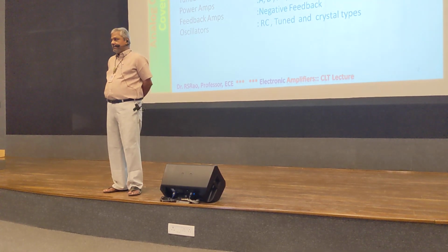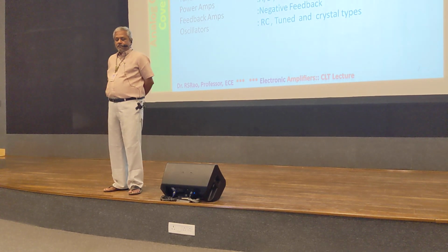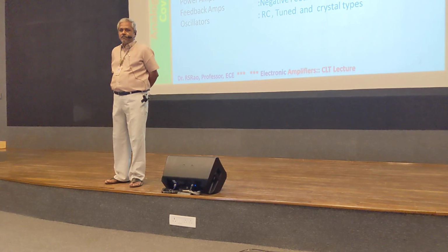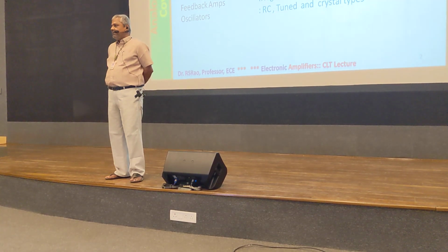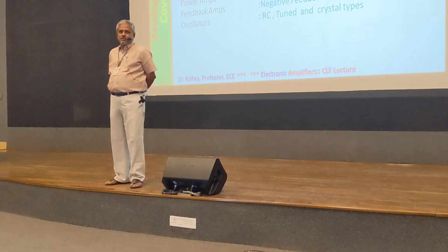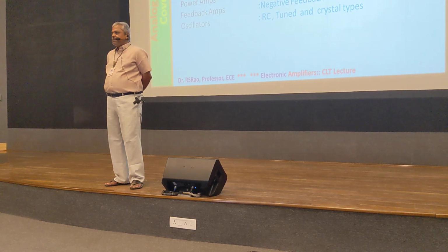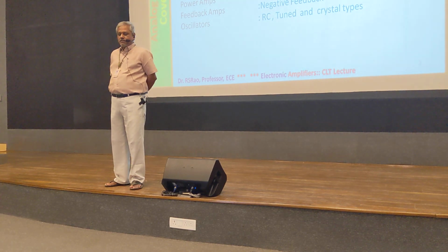But that type of situation doesn't exist in case of power amplifiers. Their voltage levels are maybe hundreds of millivolts or tens of volts. So that linear equivalent circuit business, you cannot use in case of power amplifiers.